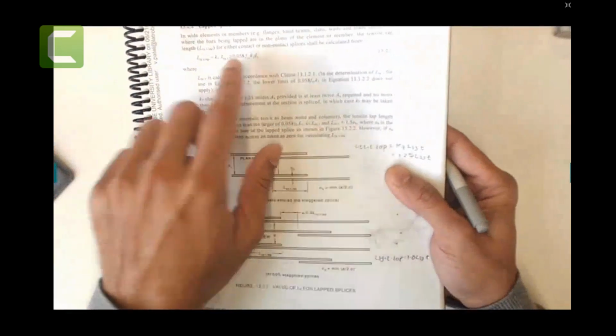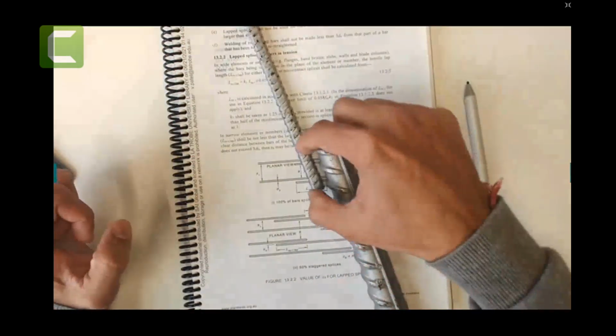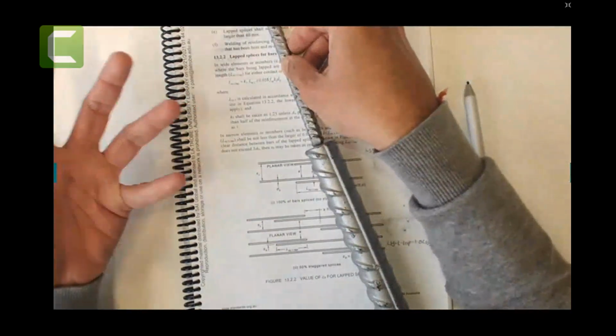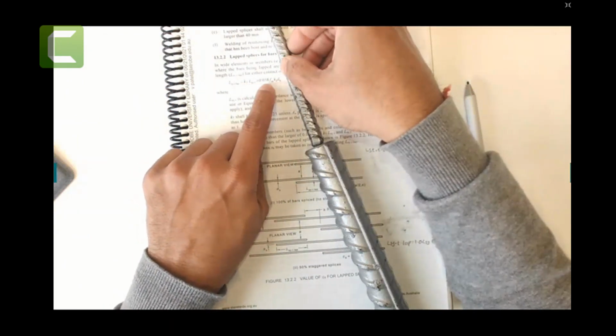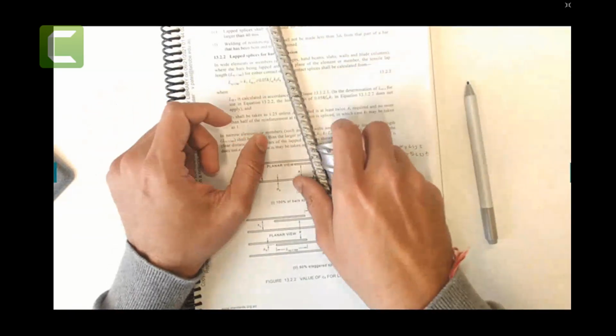As I mentioned, some smart cookies might say, I don't need to provide it. Let's do this one. Why? I make K7 equal to 0 or Lsy.t equal to 0. Then the standard says this must not be less than the minimum. You need to provide this minimum lap length regardless of your design. So that's the minimum that you need to provide. All right.